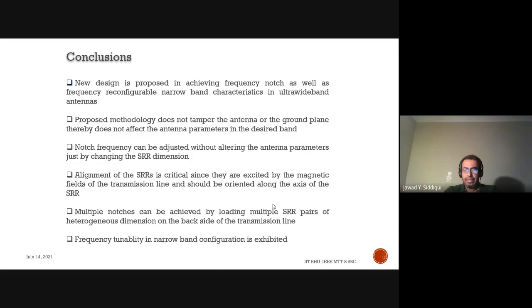And by the way, in this context, regarding split ring resonators, you can get a lot of information about split ring resonators, the design equations, from the 1956 book of Schelkunoff. If you go through Schelkunoff's book, I had that book, I can share it, I'm not sharing with you now, but I should have. In it he has explained how to use a split ring resonator, how you can design one, and what will be the resonant frequency of the split ring resonator.